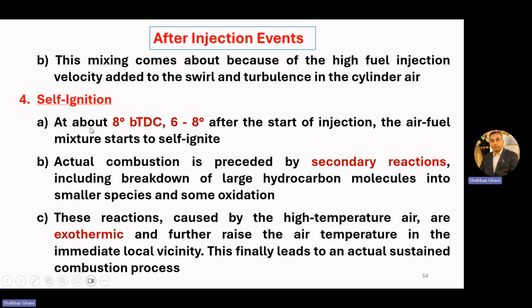So at about 8 degrees before TDC, or 6 to 8 degrees after the start of the injection, the air-fuel mixture starts to self-ignite, because we have studied that the injection time is 20 degrees of crankshaft rotation and it starts 15 degrees before TDC. So somewhere at 6 to 8 degrees after the start of the injection, the air-fuel mixture starts to self-ignite.